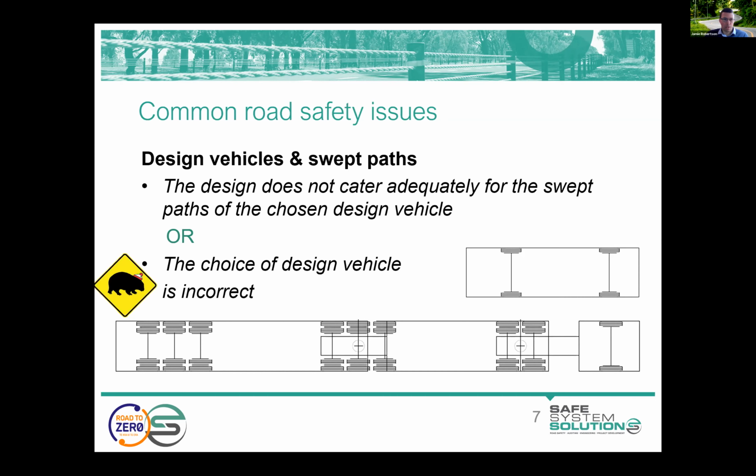And we would generally design for that vehicle to be able to undertake movements in a desirable way. So make its turns from the designated turn lanes if they are provided, and not encroach spaces that we wouldn't want them to. We also use a checking vehicle as part of our designs as well.